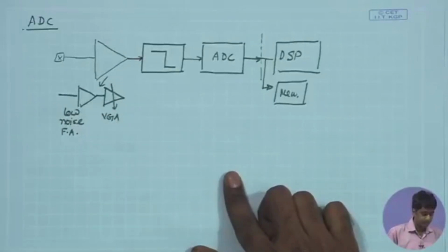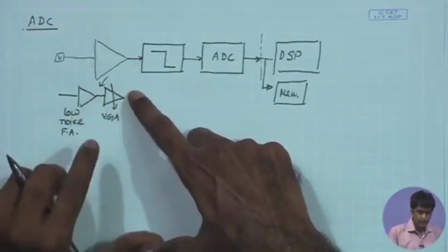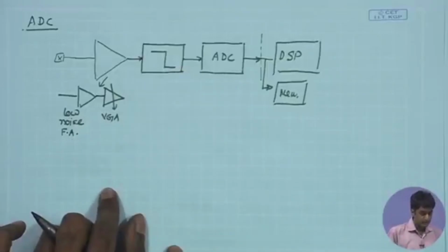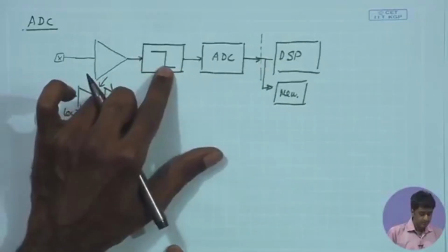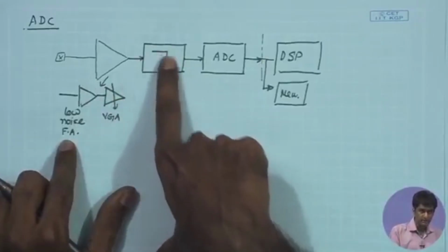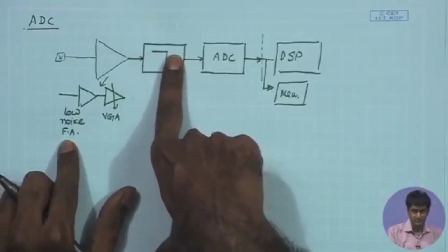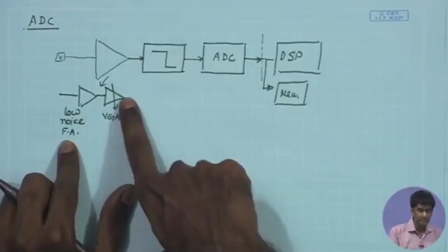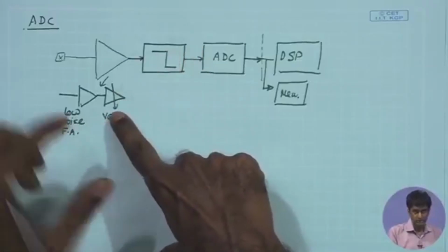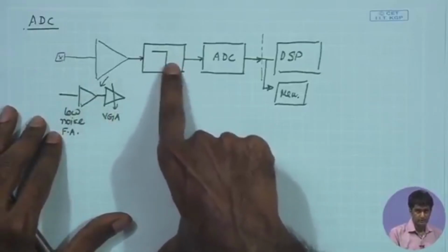What we have seen in our previous examples is that the VGA over here is capable of giving us almost full swing, and for a 2 volt supply, the swing can be almost close to 0 to VDD. In general it may be beneficial to apply the VGA after the filter, so that the circuits implementing the filter do not suffer from excessive nonlinearity, because if you give a fully amplified signal, full input swing, to the filter, that can introduce a lot of distortion and nonlinearity in the filter itself.